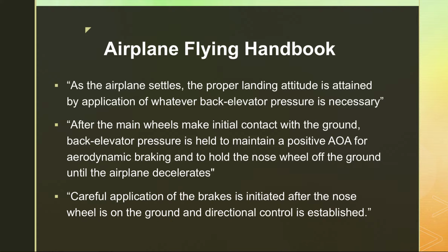And then they actually do talk about the brakes. They say careful application, not slamming on them, not stepping on them, is initiated only after the nose wheel is on the ground and directional control is established.